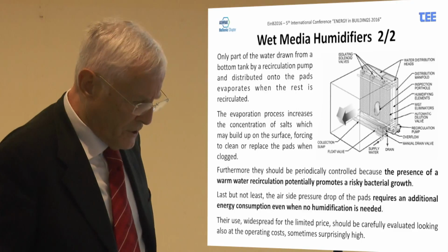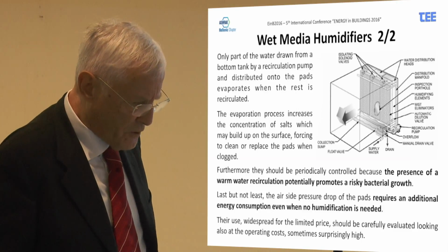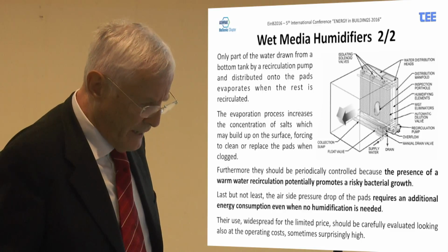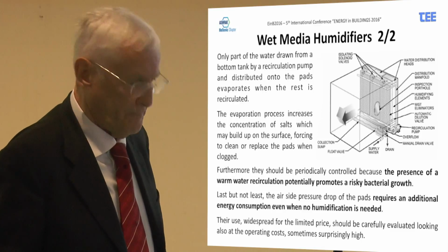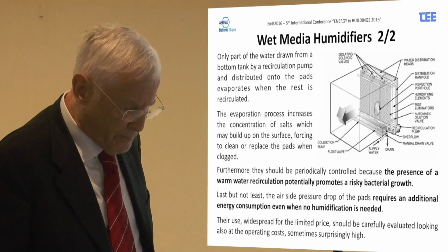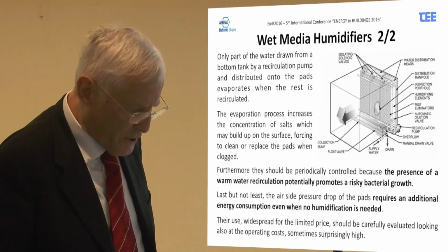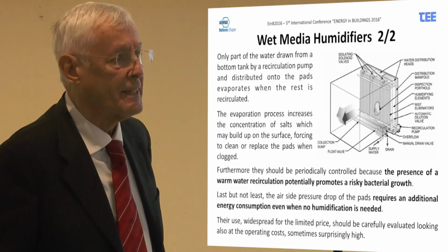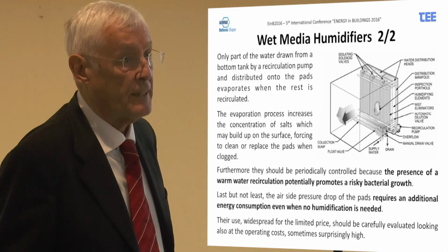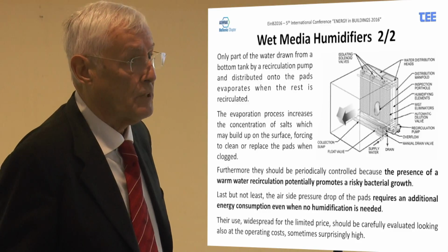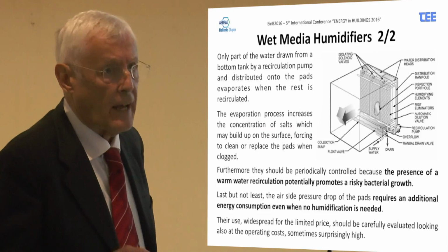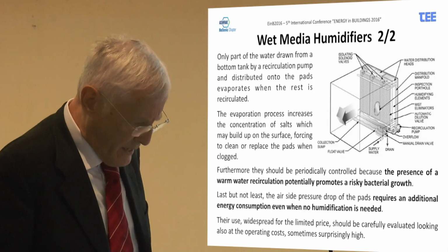The evaporation process, however, increases the concentration of salts, which may build up on the surface, forcing you to clean and replace the pads when clogged. Furthermore, they should be particularly controlled because the presence of warm water recirculation potentially promotes risky bacterial growth, because warm water with high salt content is particularly favorable to the growth of bacteria like, for example, Legionella.